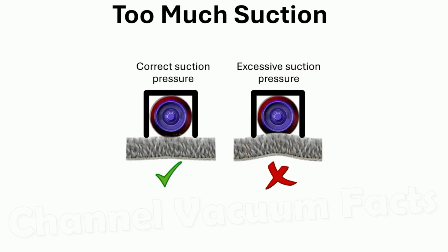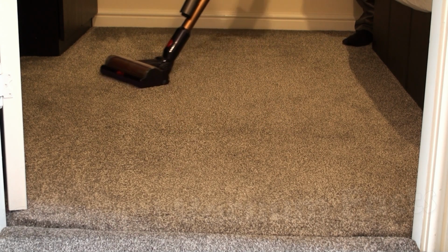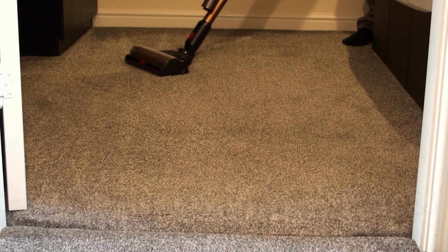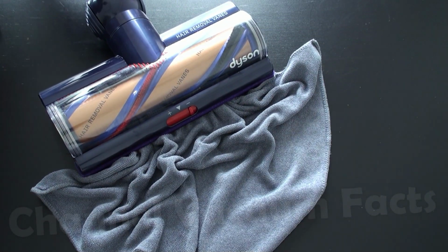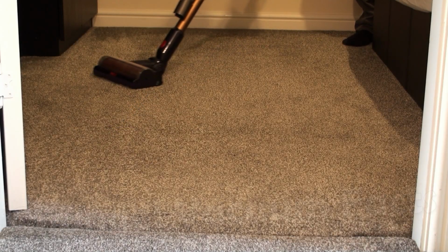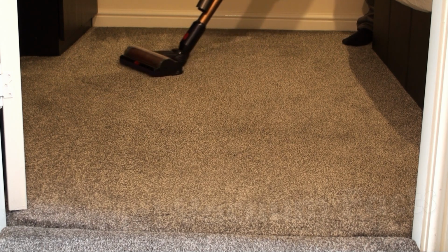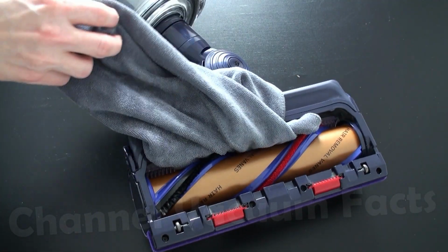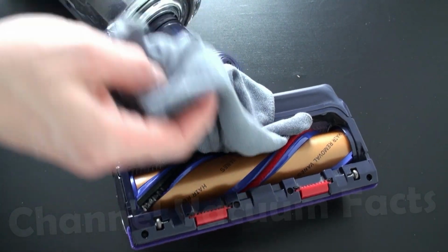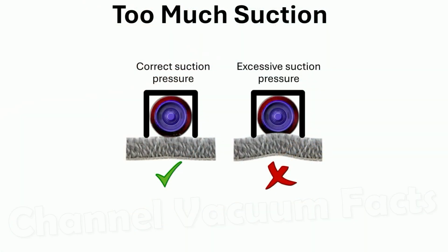If clamping becomes excessive because the head pressure is too low, the brush bar can strain as it's forced too hard onto the carpet and can draw the carpet into the cleaner head. This can cause the brush bar to slow down, and if resisted too much, can even stall. This is a built-in safety feature to protect fingers and carpets. While you could design a brush bar to brute force against this, it would risk carpet damage or personal injury. Well-designed brush bars with the correct level of stalling torque slow down on carpet when cleaner head pressure is too low, indicating bleed relief air is required on a given type of flooring, which is discussed next.